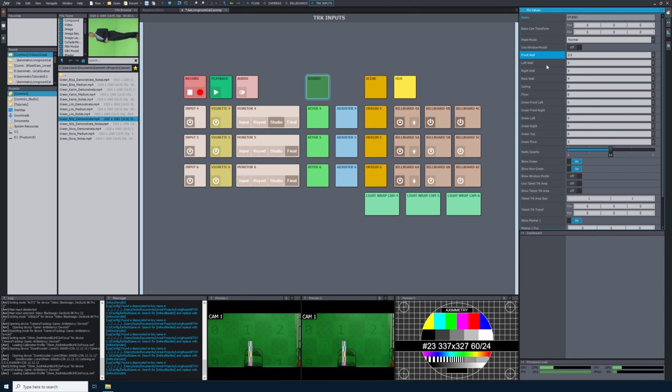My next studio wall is the left wall, so I will pan my camera to the left wall. Once the left wall is in the view of my camera, I will find the corner where my left wall and front wall meet. I will then go to the left wall setting. I will click and drag to adjust the left wall setting until the virtual wall matches my physical wall. I'm just trying to position the corner of my virtual space with the corner of my physical space. You can also achieve this using physical measurements. So you can measure the distance from the center of your Aruco marker to the left wall and then input this in left wall setting. For this tutorial, I'm just going to eyeball it.